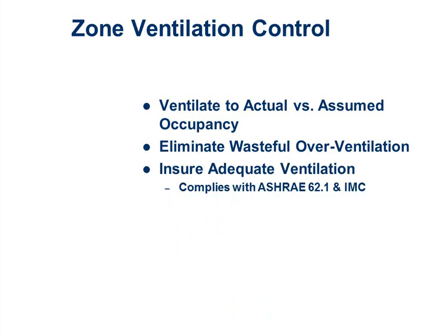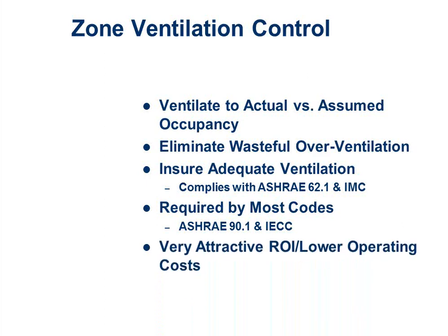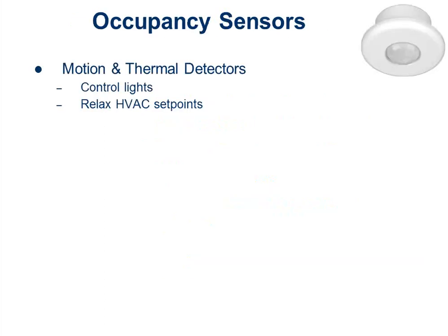We want to make sure at the same time, though, that even though we're going to ventilate less, that we still ventilate enough to comply with the codes for the people that actually did come. And we want to make sure that we comply with the energy codes, which may require CO2 sensing depending on the density of occupants in this design space. And then we want to save people a crap load of money in the end. The return on investments and the paybacks end up being a lot better now that in the past couple of years we got CO2 sensing on the rebate programs from the utilities. So that helps the payback and gets it to be pretty attractive.